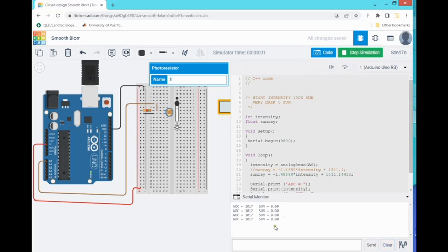0. Now let's go to high intensity. 1,000. There we go. That was a problem. The calibration curve needs enough decimal places just to be sure that it's right where we want it. I calibrated it that way: 344 was 1,000, and on the other hand, I said that 1017 was 0, so I should be able to get those numbers back the way that I set them. So the issue was this equation here. I fixed it with more decimal places, and that's it.